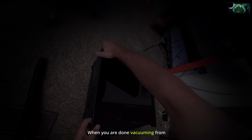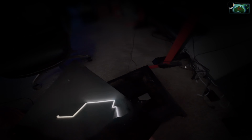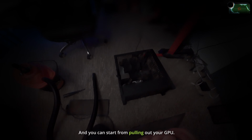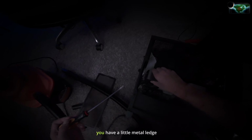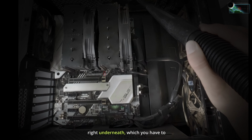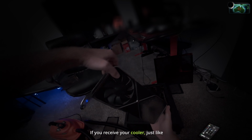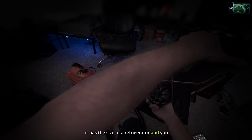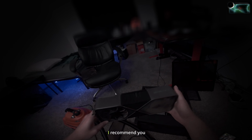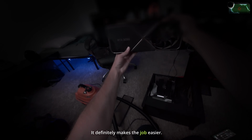When you're done vacuuming from outside, you can go ahead and open your case. And you can start by pulling out your GPU. If you're struggling with pulling out your GPU, remember, you have a little metal ledge right underneath, which you have to pull down before you try to remove it. If your CPU cooler, just like mine, is the size of a refrigerator and you're running out of space, I recommend using something like a flat screwdriver. It definitely makes this job easier.